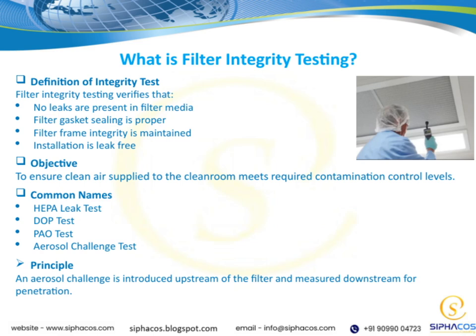The core idea is pretty straightforward. We introduce an aerosol challenge upstream of the filter. Think of it as a test spray, and then measure downstream to see if any particles penetrate through. If we detect particles downstream, it indicates a leak or failure somewhere in the filter system. This method helps us ensure that the filter is performing as it should and that the containment is effective.